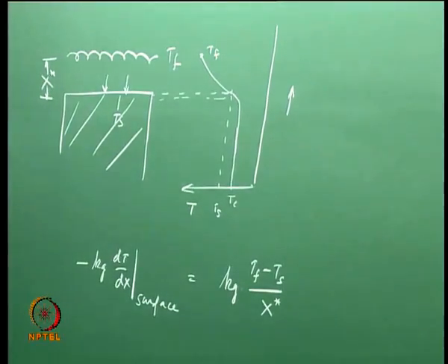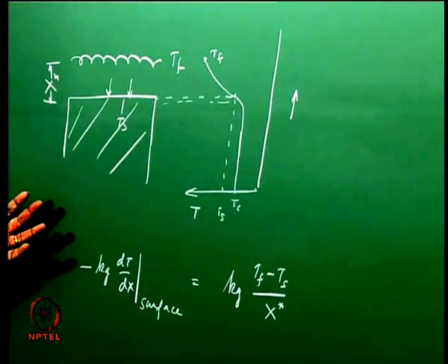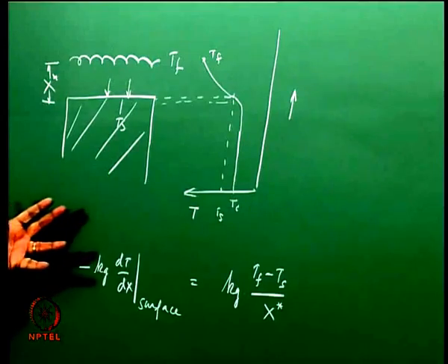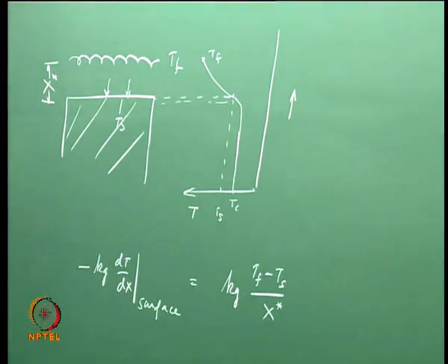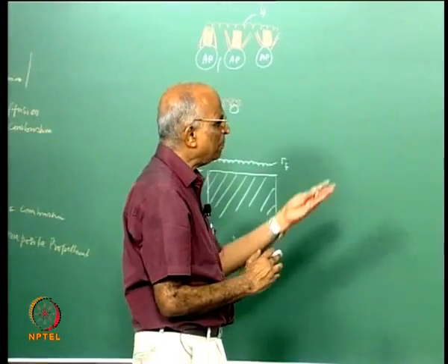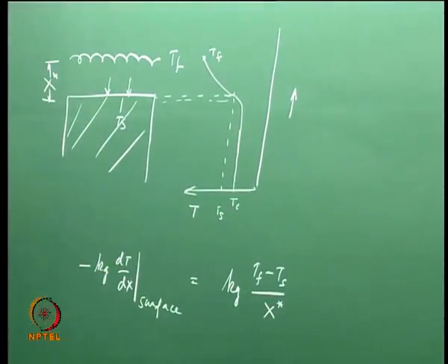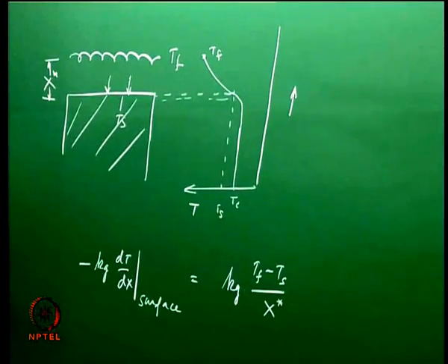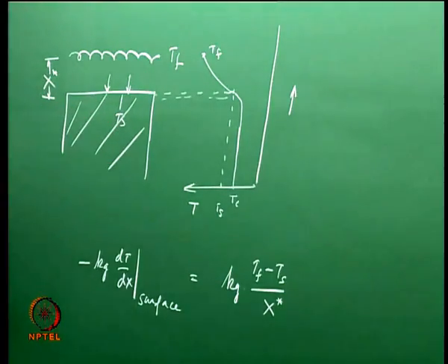This is a very simple method. There are various flame models which are used for describing the combustion of composite propellant, but this particular one was formulated by Professor Hermans. He was at Waterloo University, and it was very simple and very illustrative. Therefore, I just use this. There are various models, like the granular diffusion model or some flamelet model, but I do not see anything more coming out of those models compared to this simple model.